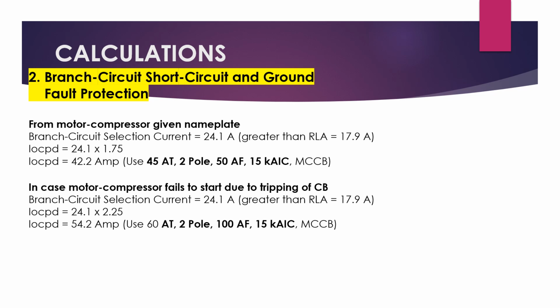This is still temporary because this value of 15 kAIC will have to be calculated during the short circuit calculations, as explained also in my previous videos. And this breaker that we are going to use is MCCB, or molded case circuit breaker.